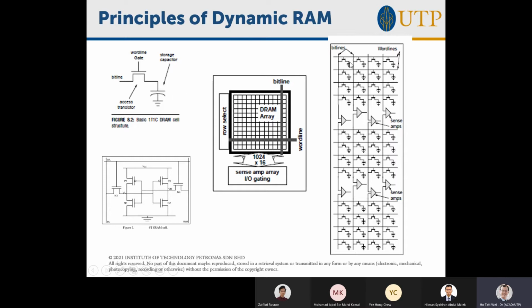So this small amount of charge is going to change the bit line a little bit higher, and the sense amplifier does a very interesting job. Number one, the sense amplifier draws power from VDD and ground. So when it sees that the bit line is slightly higher, it amplifies it until it becomes a full logic 1, which is 1.8 volts, 1.1 volts or 2.5 volts. You understand why I'm saying 1.1, 1.8, 2.5, 3.3, right? It's because in digital logic nowadays you have different logic families.